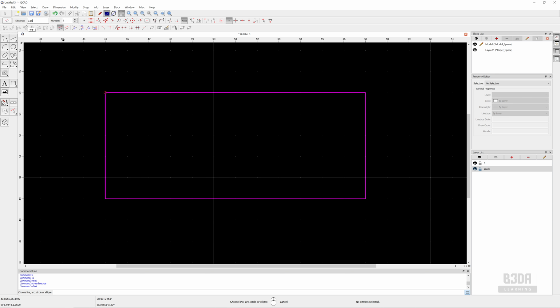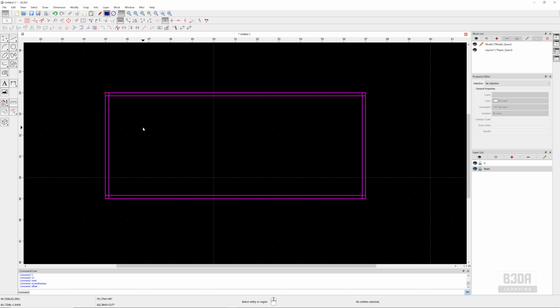Let's create an offset with 0.15, and I will make an offset from here. Just hover your mouse over the line, press right click to finish, and we can connect both of them with this option, trim both. Click on two lines and it will make the connection. Now, before making this connection, I will be creating some more offsets. First one with 0.15 and the next with 0.8 to create something like a door.